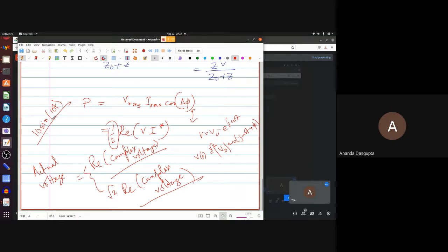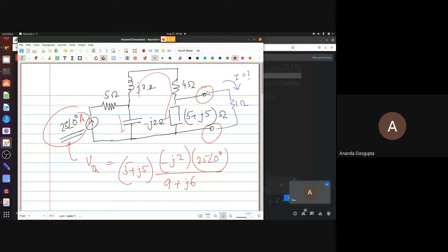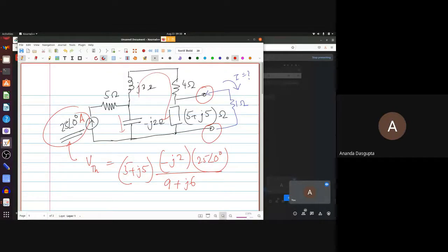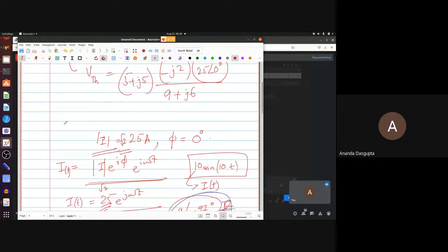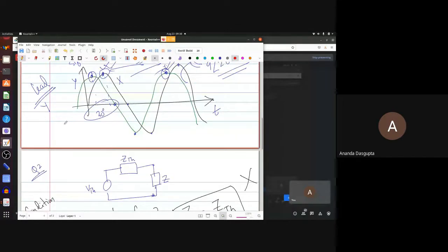On the other hand, if you're quoting the voltage like this, or like the answer that was there, then this 25 here, for example, is the RMS value. That's always the convention unless otherwise stated. So then you have an extra root 2 in your formula, which cancels out the half. Root 2 cancels out half simply because there are two root 2's. So two of them cancel out the half. Is that okay?